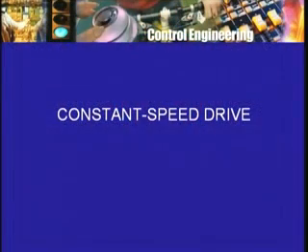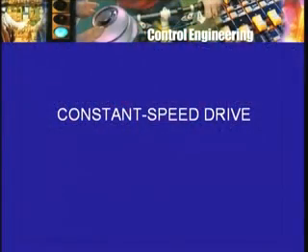Of course, the amount of material which you want to remove by grinding, the depth, also can be different. But we want constant speed. We want the wheel to run at a constant speed irrespective of the load torque changes that may take place as the grinding job proceeds. So here is one application: use a DC motor to provide a constant speed drive.